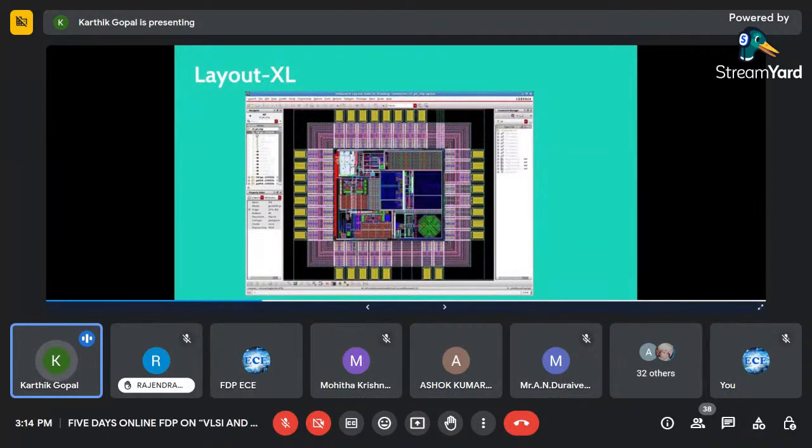The device will be on one layer, but all routings will take, let's say, up to 7 layers, a 10-layer board. Similarly, in ICs, all the connections cannot be done with one single layer in the layout particularly. Each device will stay in the bottom layer, which is called the base layer, and routings, meaning the connections between each device, and on the left side, all yellow colors are the pads. So all the connections are being done with multiple layers.